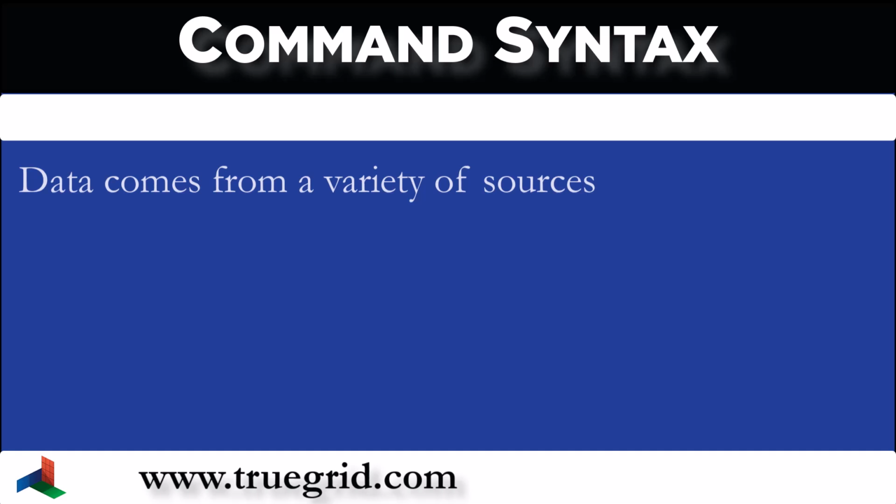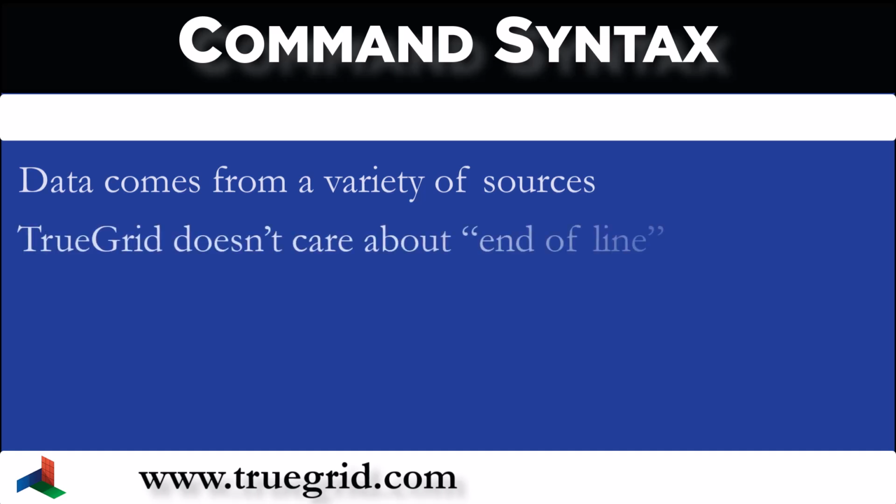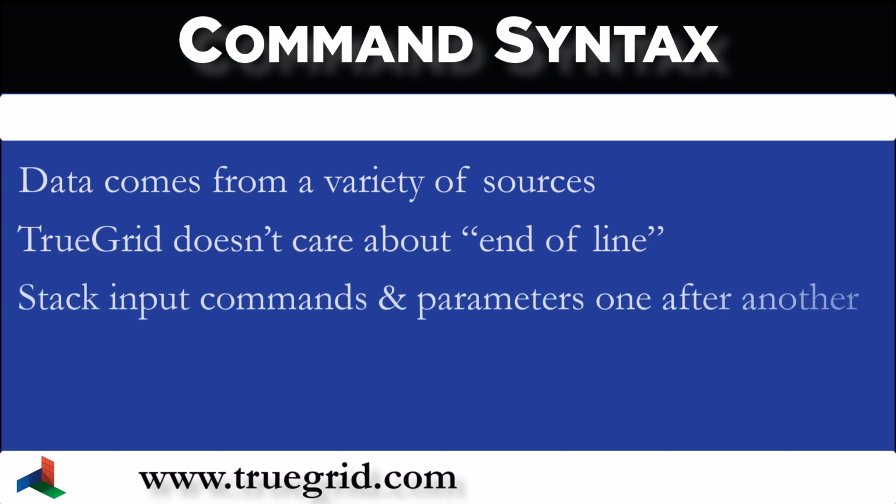Or you could be typing in commands, or you could copy some text and dump the entire file into the text window. As far as TrueGrid is concerned, data is coming to it in a stream, and it really doesn't care about end of line. So you can place many commands on one line, or alternatively, you could have one command that spans multiple lines. Like I said, TrueGrid just looks at it as a continuous stream of data. End of line means nothing to TrueGrid.